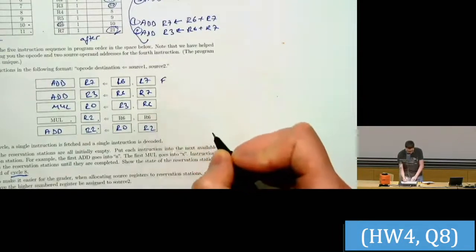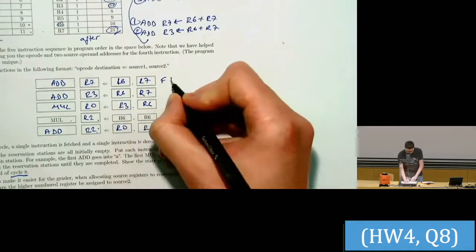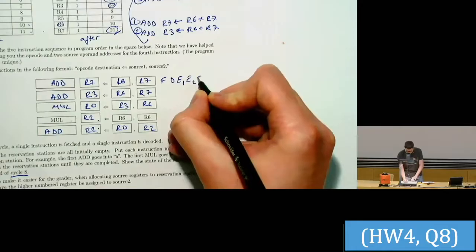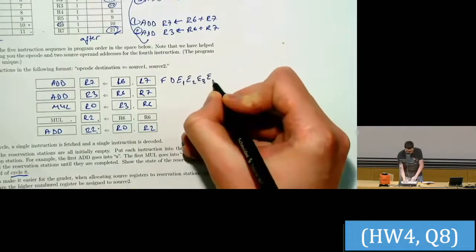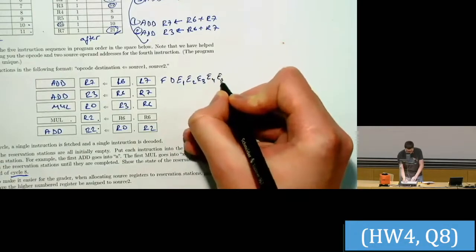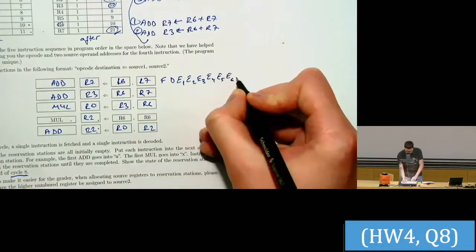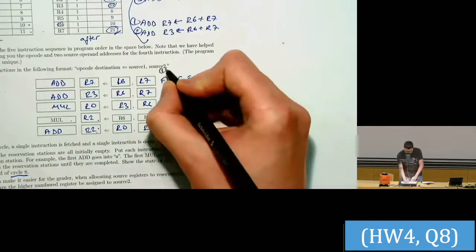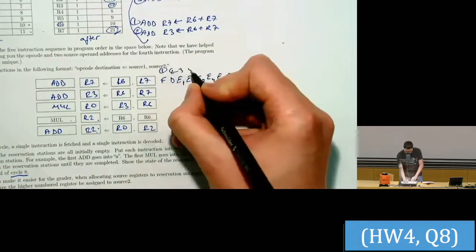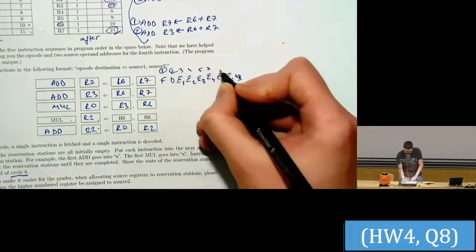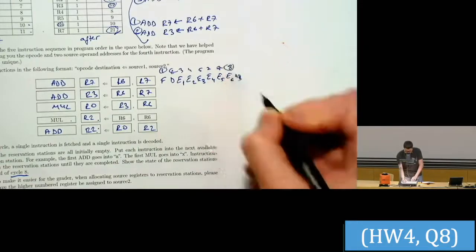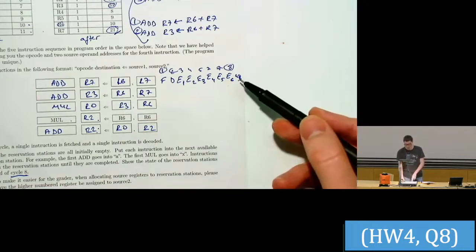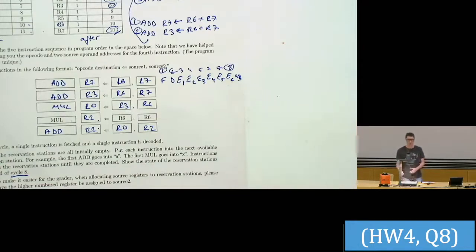So in the first cycle, for the add instruction, we will do fetch and then decode, and then we'll go through E1, E2, E3, E4, E5, E6, and then it will be right back, right? So this is the first cycle, second, 3, 4, 5, 6, 7, and 8. Okay, so cycle 8 is where we are in the last stage of execution for the first instruction.